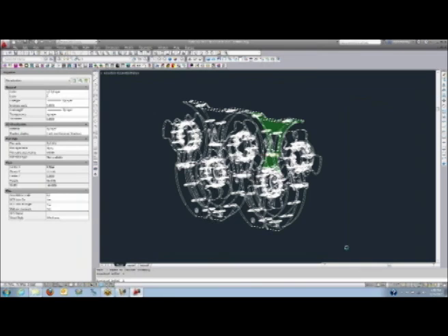and the feature recognition process begins. The parts are analyzed to decide which side should face up, based on the side that has the most machining on it. Now we do feature recognition on all sides of the parts, but one side is going to face up. If there's machining on both sides, we'll add that as a checkbox in the cut list, so the CAM system can then do two-sided machining or two-sided nesting if the parts have machining on both sides.